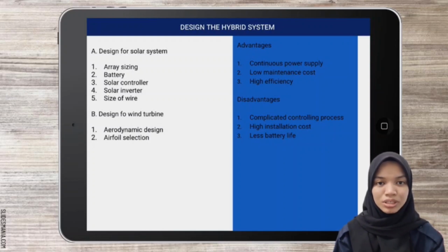These batteries are good resources to provide backup, especially at night and in cloudy weather when there is not much sunlight or wind blowing. The battery should be able to work within the specified limits, have a low self-discharge rate, and be capable of withstanding various charge and discharge cycles. The capacity of a battery depends on age and temperature. These are rated in ampere hours, and their sizing depends on the required energy consumption.